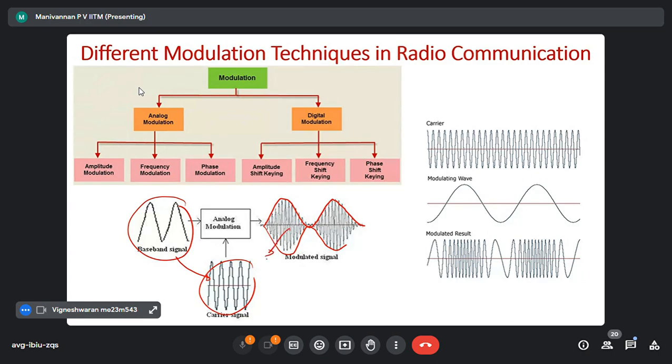This is the carrier signal. If I connect the peaks of the modulated carrier, that is nothing but this signal. But what we are transmitting is only the carrier, not this signal. My station frequency, I say, is 500 kilohertz. What is lambda for this? 3 into 10 power 8 divided by 500 into 10 power 3.